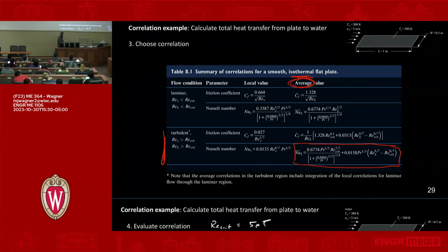What we had earlier is usually models of boundary layer thickness. You have a general form of a Nusselt number in terms of Reynolds and Prandtl. This is a very specific set of correlations for this type of problem. So the way you generally know is if you can find a specific correlation for your problem that matches really well, you'd use that specific set. This table happens to exist, it's perfect for what we want, so we use this. If this doesn't exist, then you have to go to your own experimental data, or an approximate model, or just something that looks kind of similar, that has similar characteristics, but doesn't exactly match. And in all those steps of removal, you're introducing uncertainty in your solution, basically.